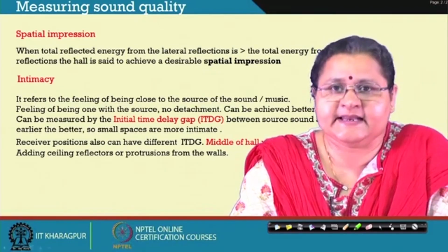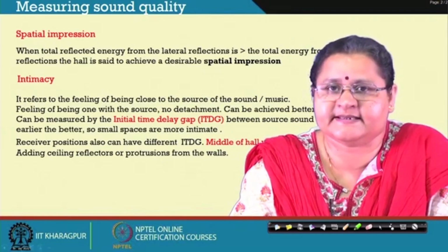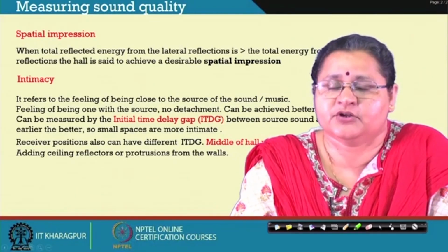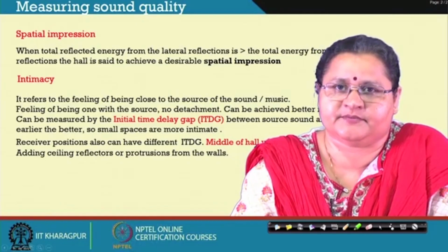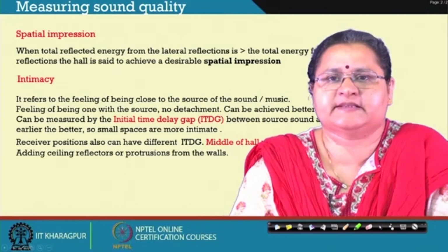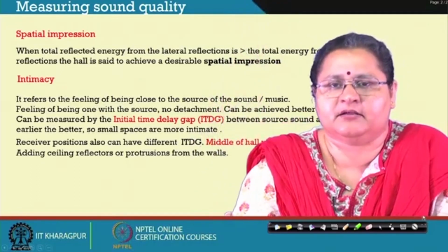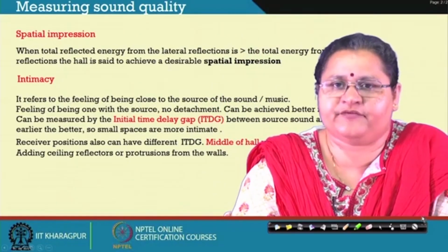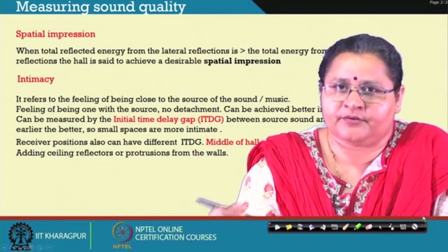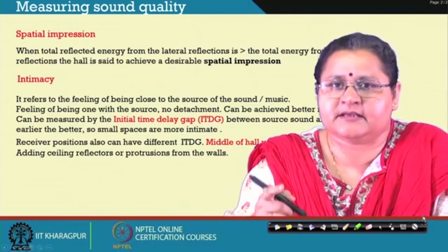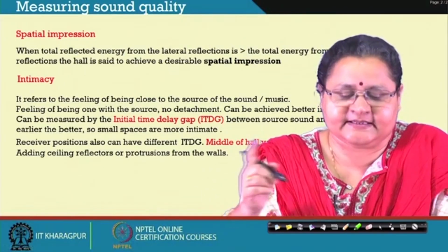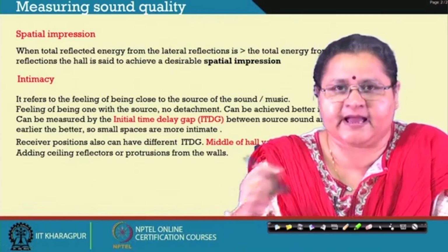You can add ceiling reflectors to reduce the distance to achieve better intimacy, because the side walls are fixed, but some overhanging items from the ceiling which act as reflectors can help in reducing this ITDG, that is initial time delay gap.